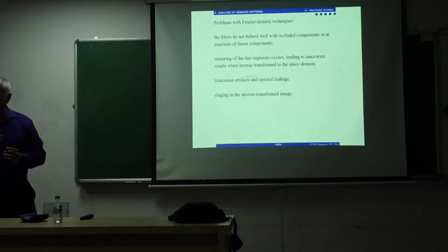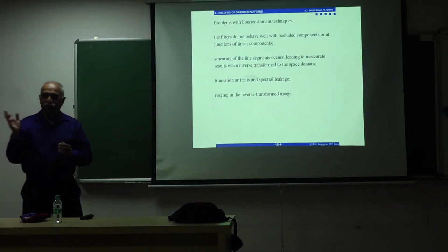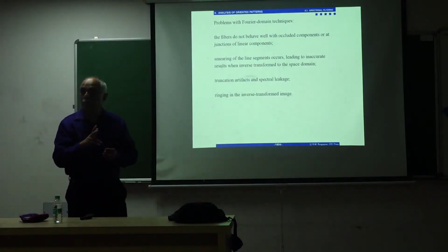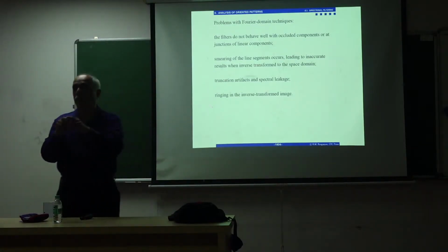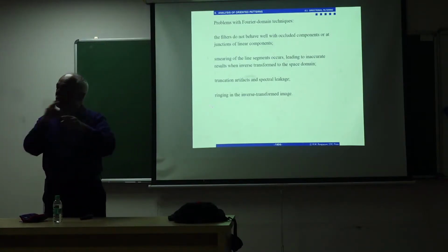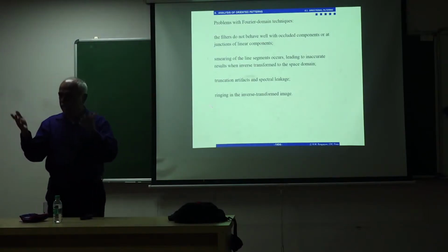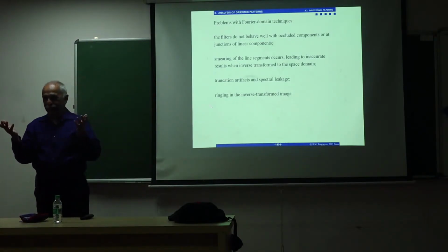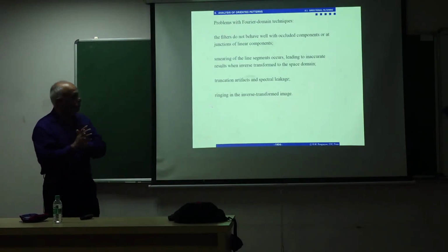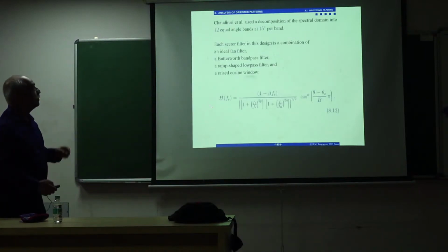The same thing happens in 1D. When you truncate a signal, the spectrum is not the real spectrum anymore. And truncation may not be by applying a window, it is just that we start observing here and stop observing there. Signal has been going on. So that is a window, an implicit window. So there are these artifacts.